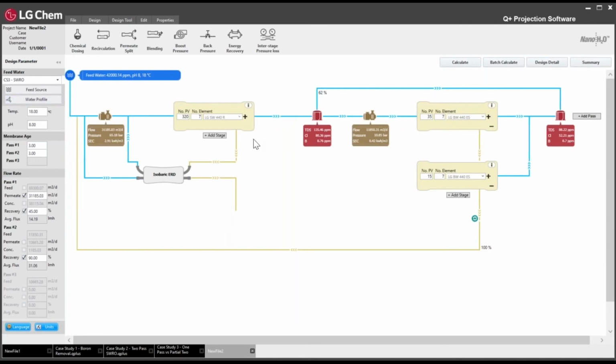Even at 18 degrees, for example, you'll note that the permeate chloride in the first pass is still less than 154 ppm. Because it's still less than 154 ppm, what this means is we can actually operate the two-pass design as a single pass at 18 degrees and potentially higher, right? So basically, we want to see at what point we hit approximately 154 ppm chloride, right?